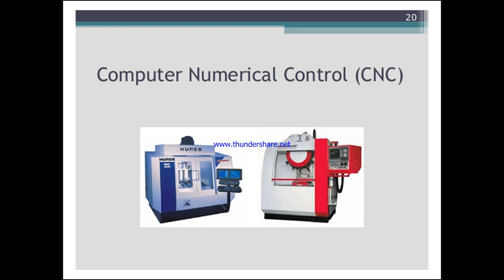So all numerical control machines manufactured since the 1970s are of CNC types. So the computer allows for the following: storage of additional programs, program editing, running of program from memory, machine and control diagnostics, special routines, that is in terms of inches or metric, incremental or absolute switchability. So by all these we can control the computer where it is we are having.